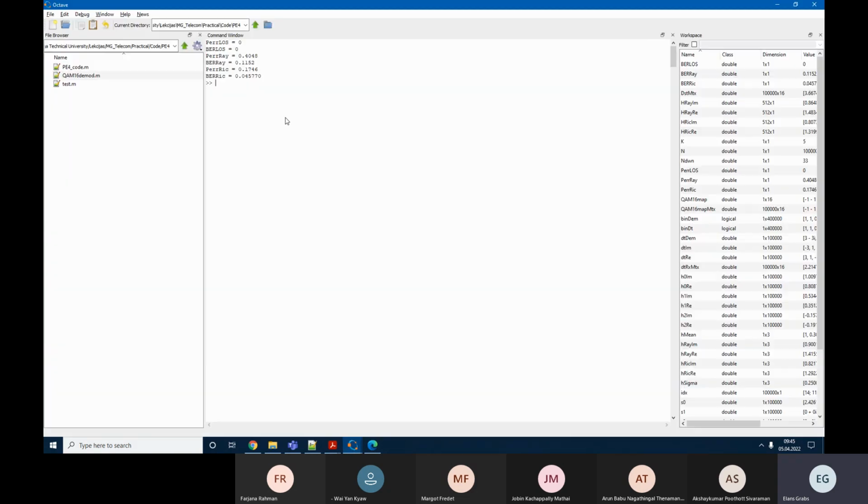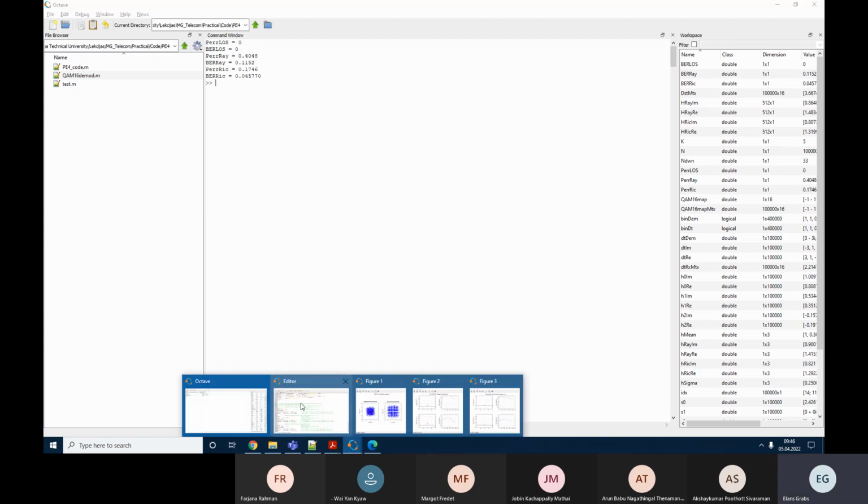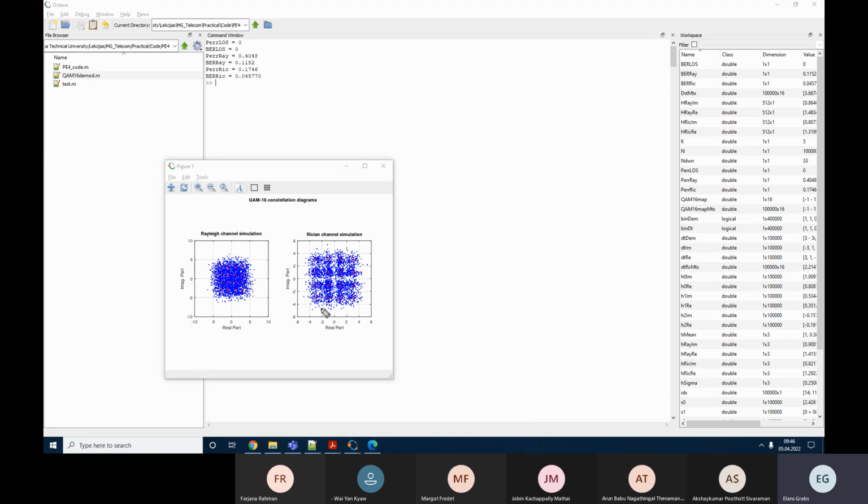Now, please also note that we didn't get zeros. Yes, we don't have noise, but at any rate, there is some probability of error, which is much smaller now. As I said, because we are using gray mapping, and we actually transmit 4 times as much binary data compared to symbol data, and usually one symbol error produces 1 bit error, right? And here it's also quite possible to see that the situation is not so dramatically bad, yes, because we can see shapes of the clouds forming that can be detected more or less correctly. Still, there are cases of incorrectly detected symbols, right? Meaning that it introduces more than 1 error per bit, which is some statistics, right?